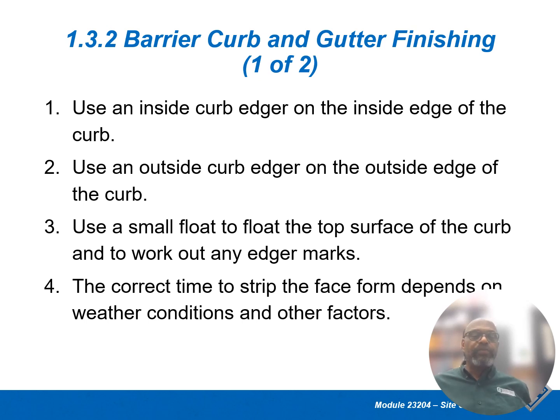So number 3, use a small float to float the top surface of the curb and to work out any edger marks.